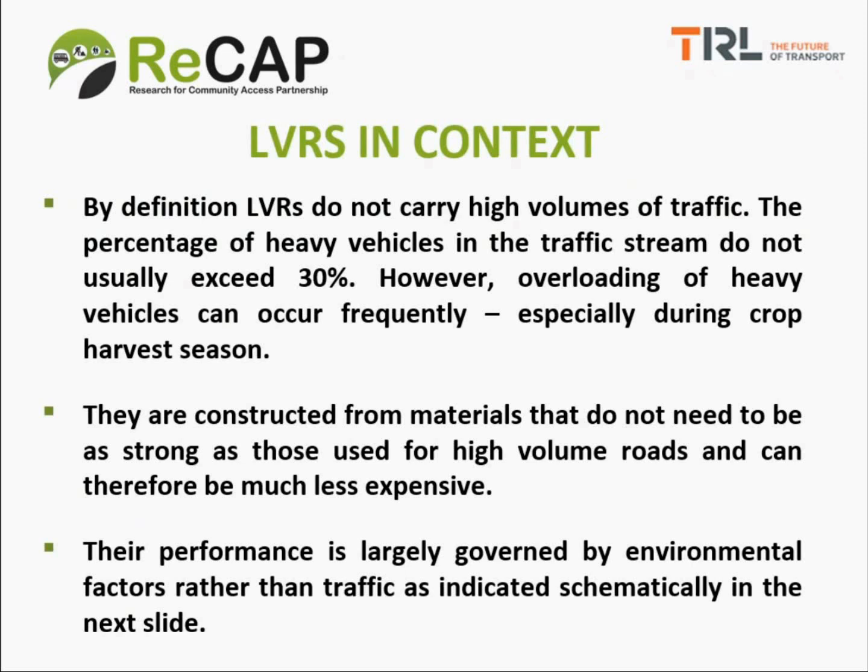And of course, it's very difficult to control that overloading or those heavy vehicles. Some countries have tried to prevent overloaded vehicles from travelling on the rural roads, but it's generally not been very successful. So there's always a risk that our low volume road will have to carry a few heavy vehicles, especially, as I've said here, during harvesting season. Add to that also any season where people are building, materials are heavy and so on, and logging is another process that actually causes vehicles to be heavily loaded.